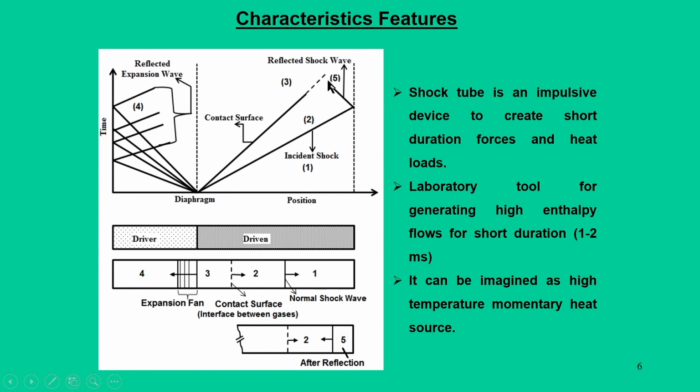Now, when it reflects and you extend this line, this is the time the incident shock hits the end wall, and this is the time the reflected shock meets the contact surface. So, this time duration we can mark as the test time.